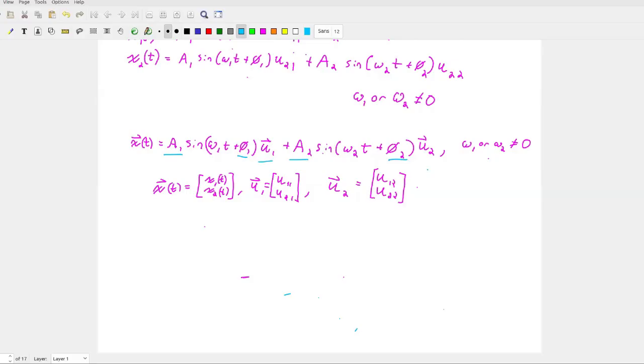And then U1 and U2, those are our mode shapes, the first and second mode shapes, and that's what couples the system together. If you don't have the mode shapes, you don't have your system coupled. You can have 2 1 degree of freedom problems, but you have to have the mode shapes to couple your systems together. So that's the solution that we are working to. So now that we know where we're going to end, if you don't write much down, write this down. So now that we know where we're going to end, let's work our way there.